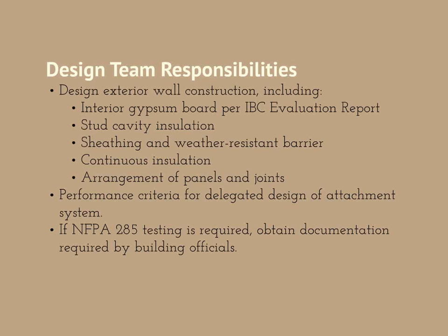But one manufacturer that I know of that has done the 285 testing for ACM systems, they have their own line of continuous insulation. It's a polyiso, and it's dense enough that they can actually connect their system through the insulation to the studs without having to have the Z-girts in between. So you do have to pay attention to it, and I guess that's really the point of most of this. But other manufacturers throw up their hands in horror at that thought.